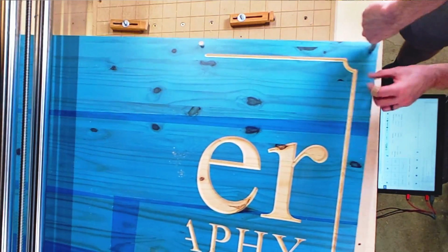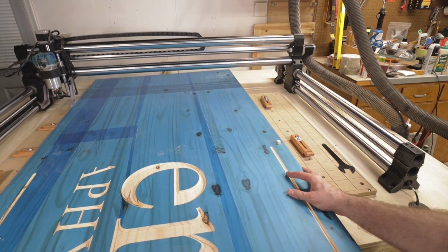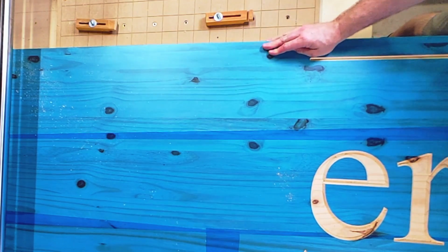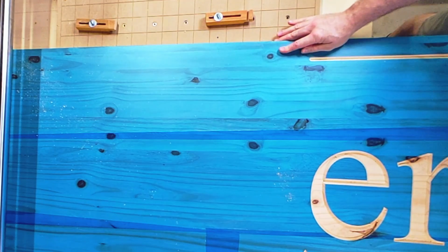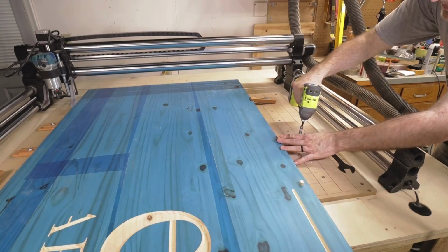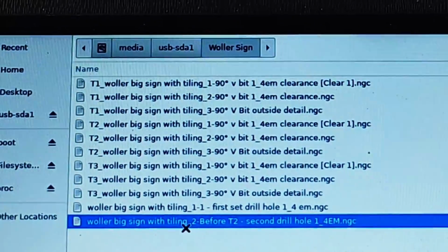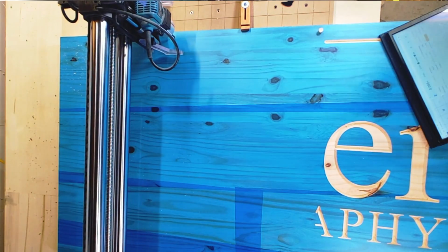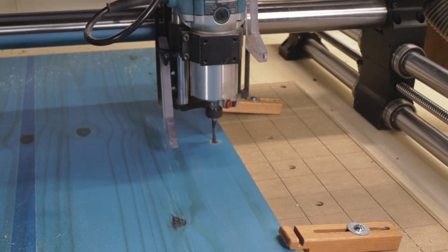So pull up your workpiece and slide the second dowel into the first hole that held your first dowel. And be sure to line everything up again and clamp it down. Alright, next we need to drill a third guide hole through our workpiece, right where the second dowel used to be before we moved it down. That way when we move down to tile 3, we have a dowel ready to go to slide into that original spot. Now we're on to the second tile.